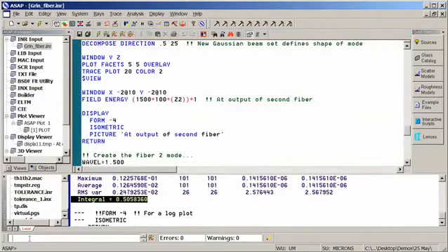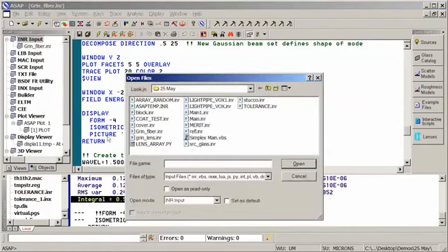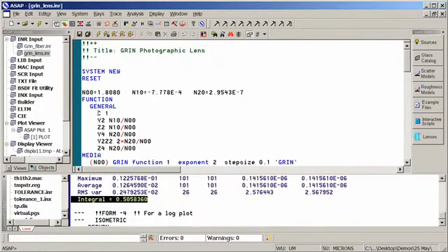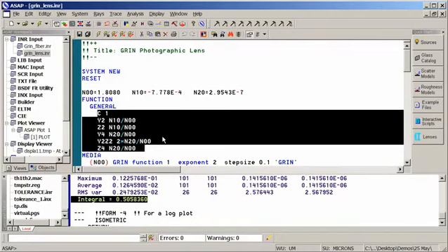In addition to optical fibers, many optical systems have lenses made of gradient index materials, and these are a more large-scale version of gradient index. Obviously, the grin fibers tend to be much smaller in diameter. But we also have gradient index lenses, and to define a gradient index material, you'll simply need to define the manufacturer's parameters that describe the properties of that optical material and define a media that then uses those properties.